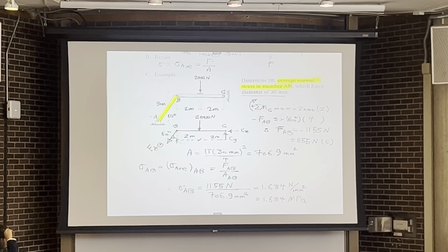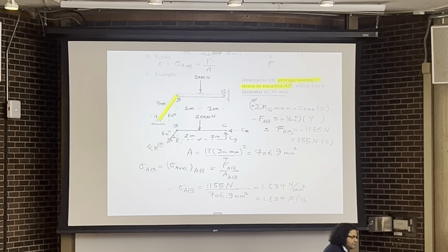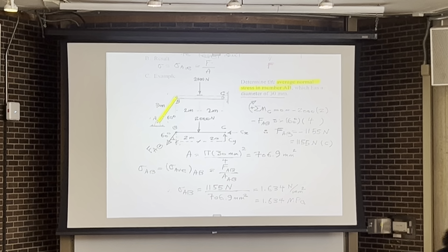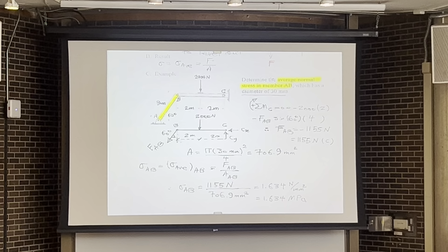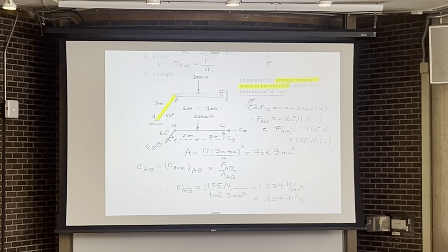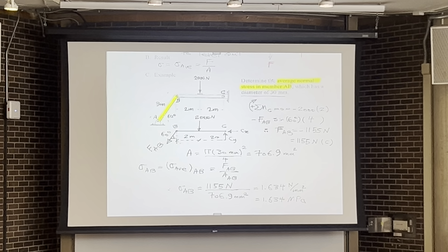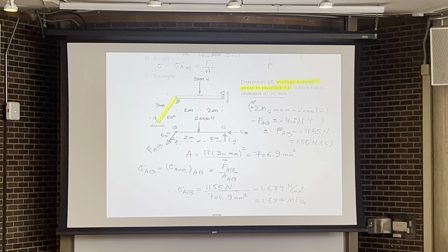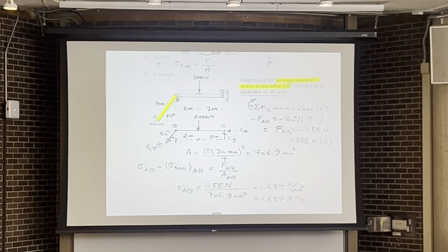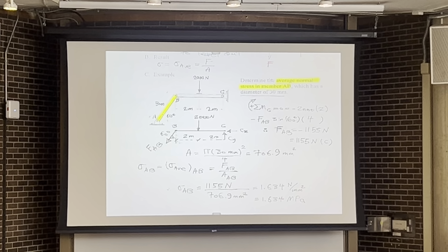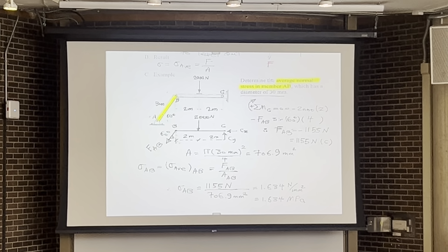Yes. So, is that force AB being in tension or compression with that stand? No. Again, it's a good question. The answer is no. As long as it's an actual force, either tension or compression, we can just simply divide it by area, and that will be a normal stress. So we have two types of normal stresses: tensile stress and compressive stress. This one over here is a compressive stress because it's because of the compression force.